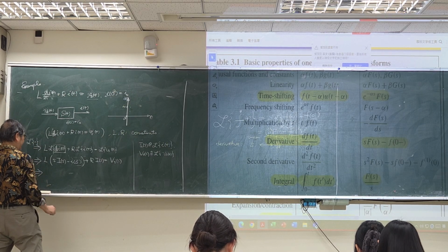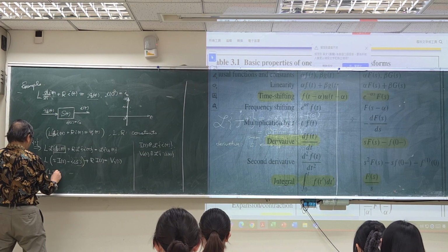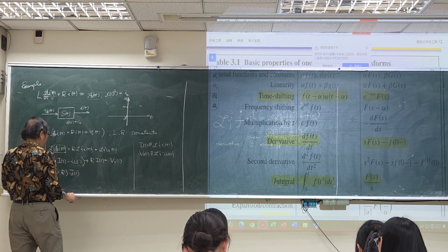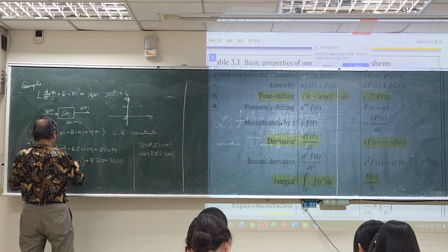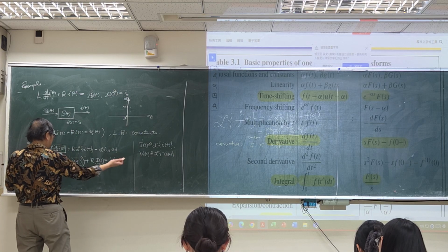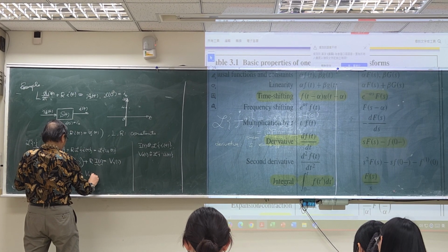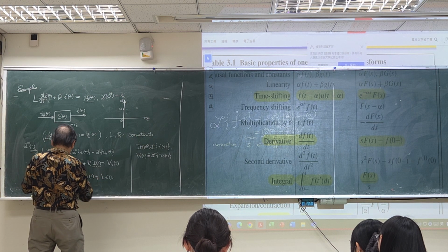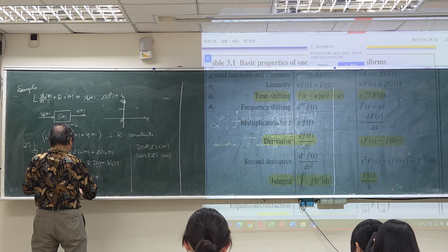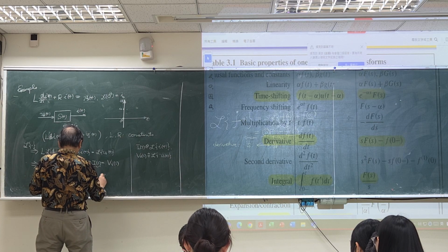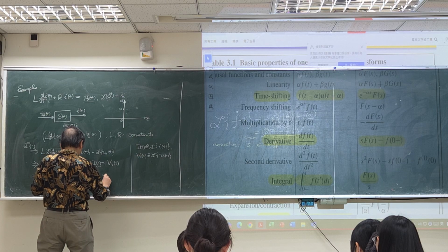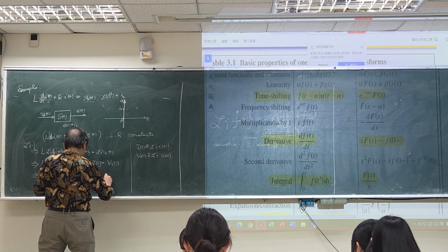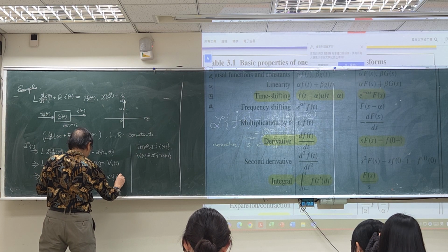Okay, so what we have here is Ls plus R times I of s. Okay, that's the addition terms, right? And then bring the integrator to the right hand side, now equals to Vs, and then plus L times the Laplace transform of the initial value.